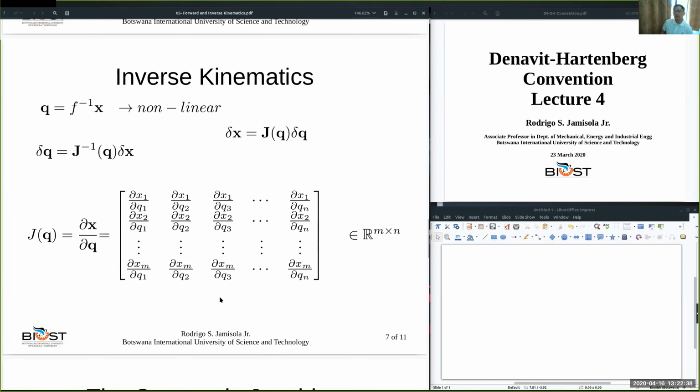Now, let's go to inverse kinematics. As we mentioned, we use x as our desired location in the workspace, and then we solve for a q that will give us that x. What are the joint values for each of the robot joints, so that we can have our hand in the world where this is x? And so again, this is the forward kinematics linearity equation.